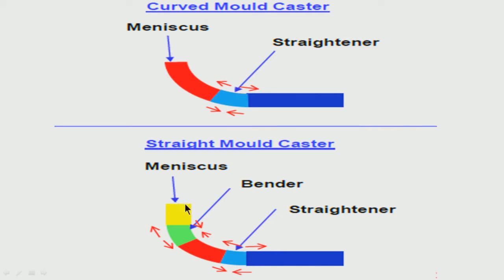That means, when there is a liquid slag here at the meniscus level, it will get absorbed. But here what is going to happen? When they are floating up, because solid shell has already formed, there is a possibility of some inclusions getting entrapped in the solid shell which is forming during initial stage of solidification. So, here that possibility is not there because it is going vertically.